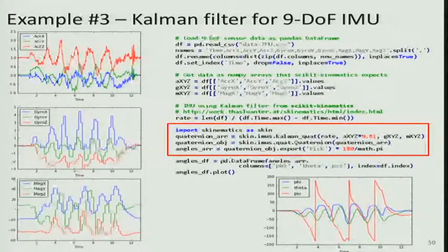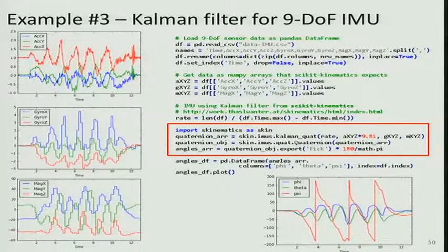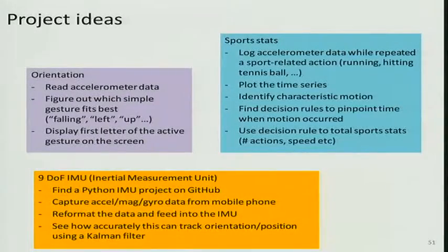So taking noisy 9-axis data on the left-hand side, here are heading angles as I've held my phone and wiggled it up and down, walking in circles 3 times. The angles wrap around 360 degrees as I turn in a full circle. But this is really simple to use. The maths for doing rotations is a bit cumbersome, but packages like scikit-kinematics make it quite easy.